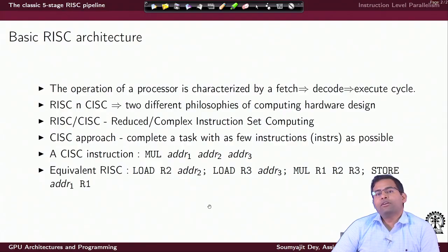happen over data values that are present in the register. The result of such operations shall also be stored in registers. There is no operation that is going to happen on values stored in the memory. So, the only instructions which are going to write or read data from memory are the load and store instructions.